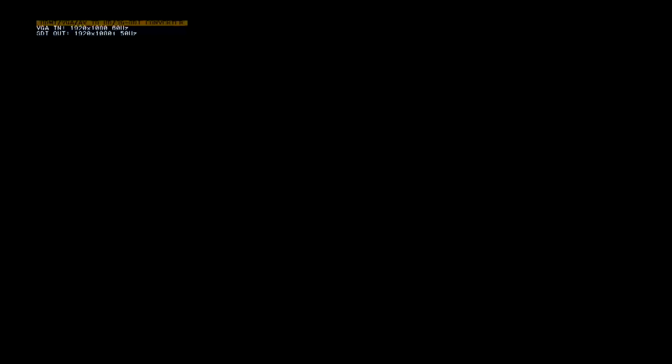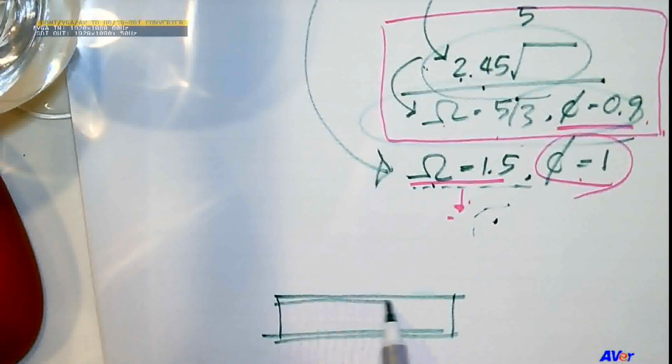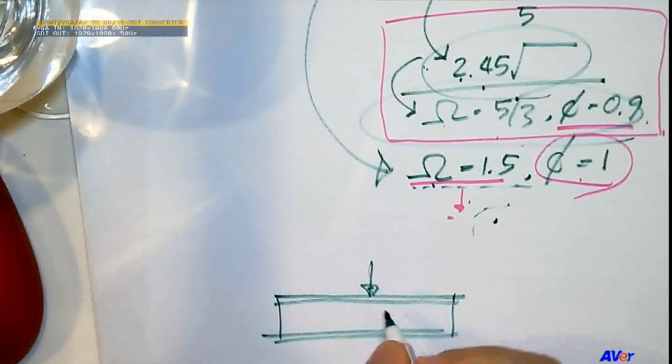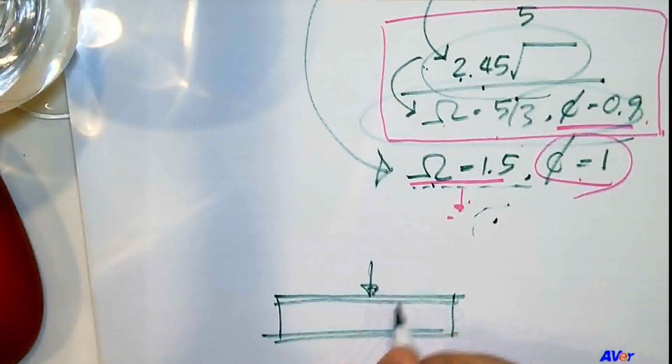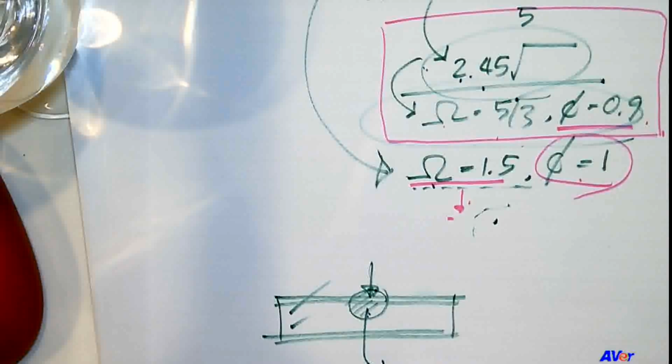If the point load is so large, this point load will cause moment, it will cause a shear, and it can also cause the local failure underneath it. Okay? So when you have a situation like this, you need to make sure that your beam will survive bending, flexural shear, and local failure.